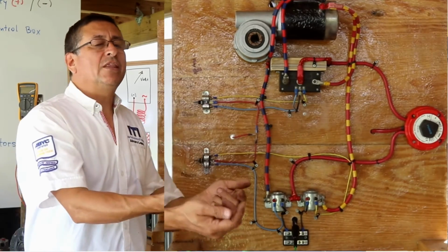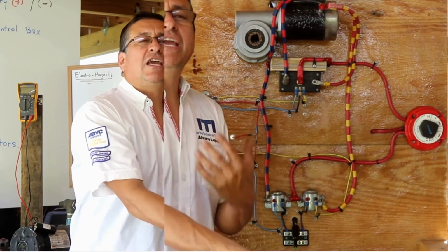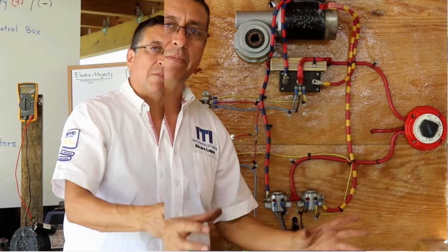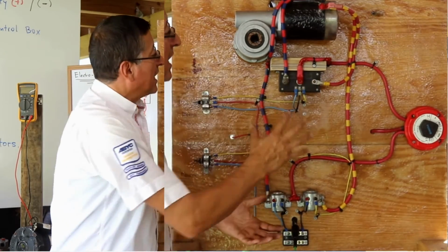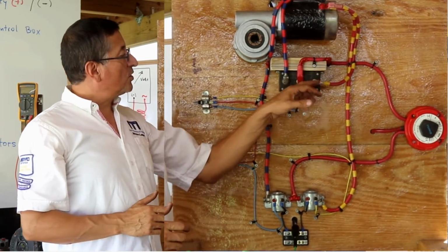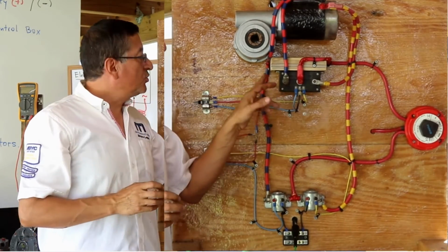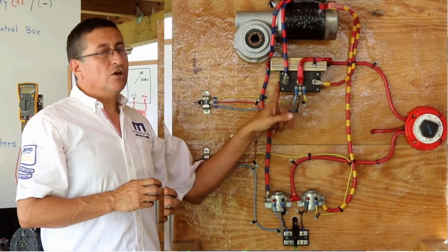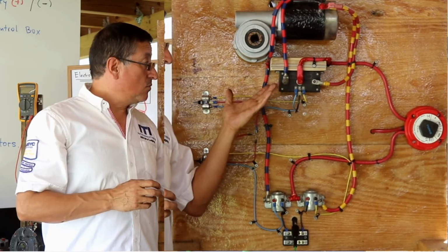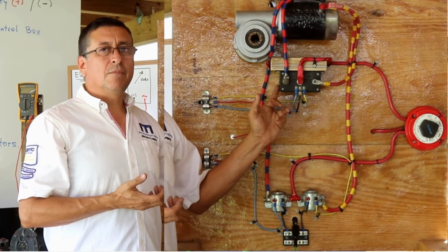You remember that when the anchor is coming in, the chain is coming with water and splash water when the chain enters the compartment. That water splashes and corrodes the solenoid control box. The majority of the solenoid control boxes after 2 years are fully corroded and should be replaced. Those solenoid control boxes are expensive elements. It's more than $300 depending on the quality.